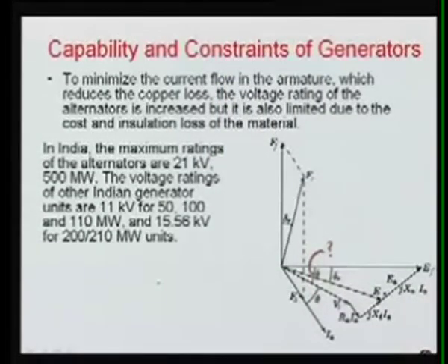We have seen another constraint, a limiting value of the alternator: the voltage due to the dielectric and the design limits. So various limits are imposed on any element. It may be the thermal limit, or heating limit, and another is the dielectric constraint. Now this alternator is basically called doubly excited, meaning we have the field winding, to which we give DC field on the rotor, and we have the armature where AC is produced. So we have the field MMF and the armature MMF, meaning we have the MMF at the rotor, called Ff, and the MMF of the armature, Fa.